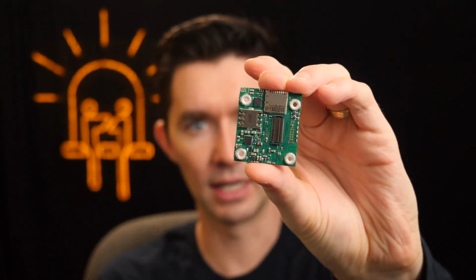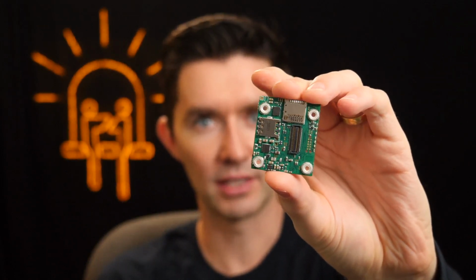One other thing I'm excited about with this, obviously on the back side here, it has not just the SD card holder for memory and the SIM card holder over here for talking to the network. It also has a charge chip on here that works with cellular and, of course, works with solar. It has an MPPT, or maximum power point tracking, algorithm on there, basically to be able to work with the solar panel and charge the battery attached to it at the maximum amount out in the field. And so that's another exciting thing there. All these things kind of work in conjunction.